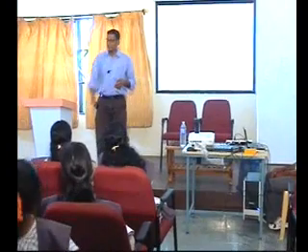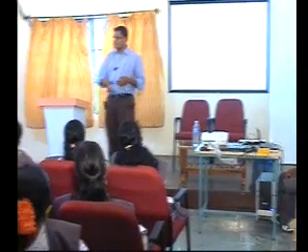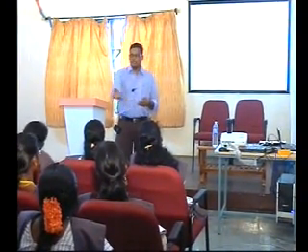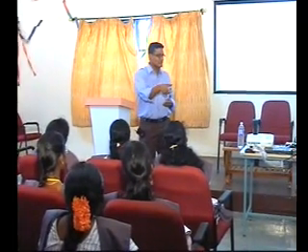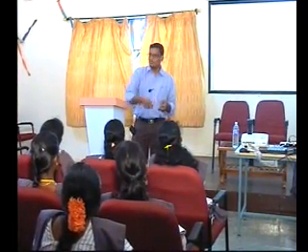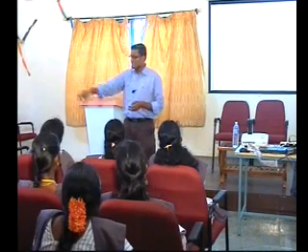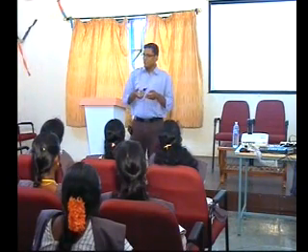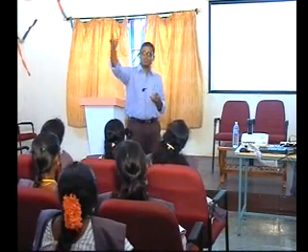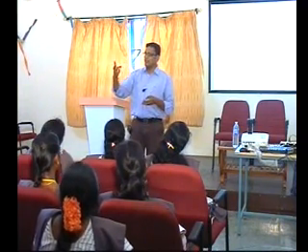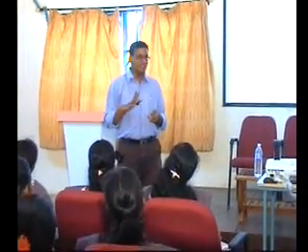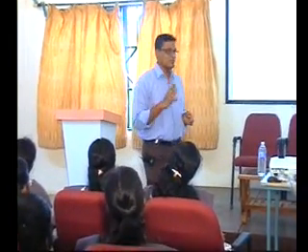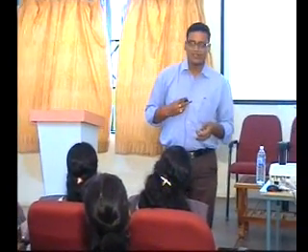Now, just now I have given one test vector to this group of students: 0, 1, 0, 1, 0, 1. This is a vector. After that, if I use 1, 0, 1, 0, 1, 0, this is another vector. So I will use test vectors, test the locations, and identify whether the memory location is faulty or fault free. This is called fault diagnosis. What do you call it?